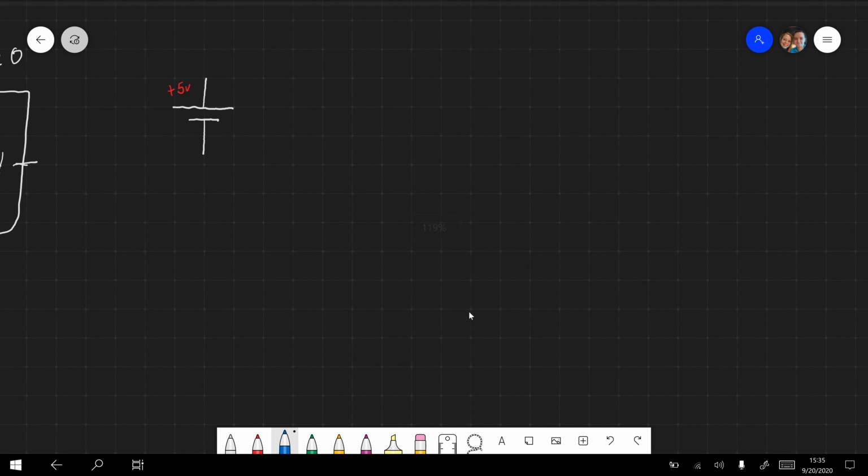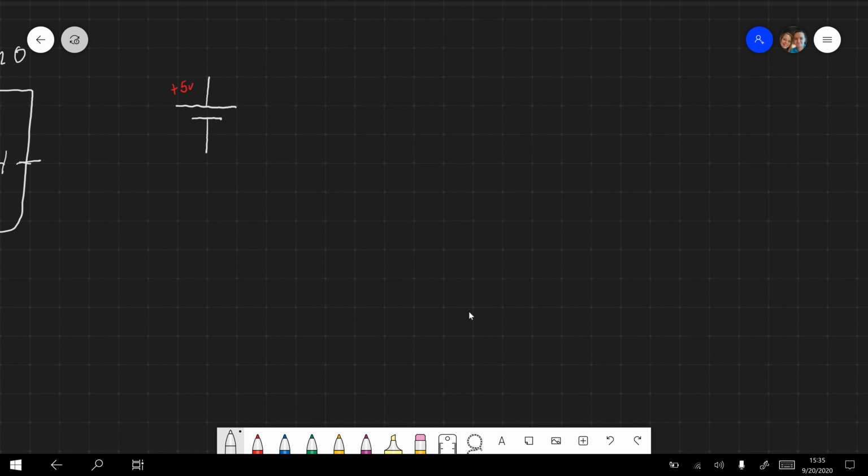And then let's talk about maybe a resistor. A resistor looks like this, just a zigzaggy line, and it's a good idea to label all of your resistors. So I'm going to say that this one is a 100 ohm resistor, and I'm going to put this omega symbol here, and that just stands for ohms. It's the measurement of how resistive this resistor is. And yeah, it's a good idea to label that.